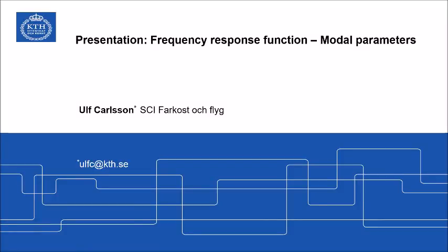In a previous presentation, we saw that the forced response vibration of the system can be expressed as a linear combination of the system's modes. In this presentation, we will continue and develop this expression a bit further. We want to reach an expression which clearly and explicitly shows how the frequency response function, or system transfer function, depends on the mode parameters of the system. This expression we will use later on when we wish to identify the system.